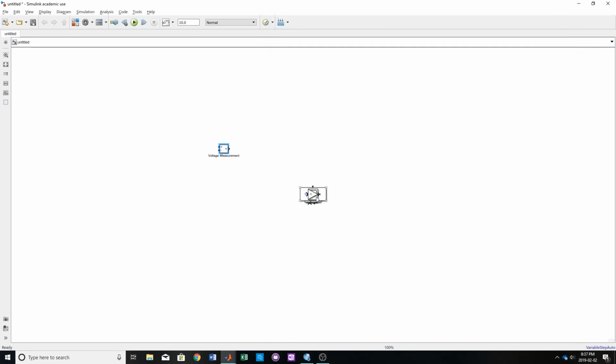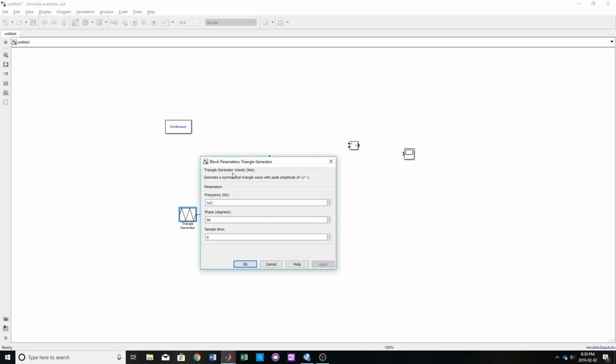Now we're going to just demonstrate this waveform on a oscilloscope. Okay, you're going to just keep this block anywhere you want. You're going to set it up like this. Have your ground, your controlled voltage source, and your measurement device. Okay, now we're going to first connect the triangle wave generator into the gain block. Okay, now the gain block is used to increase the amplitude of the generated signal. In this case, the signal generated will be a amplitude of 1.